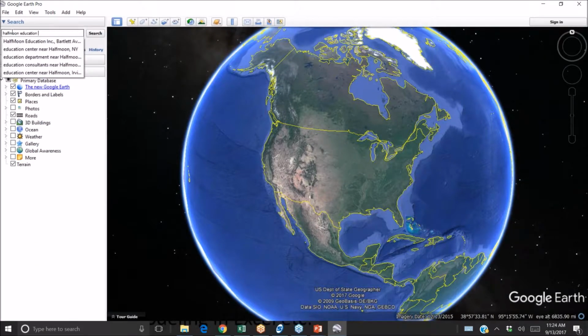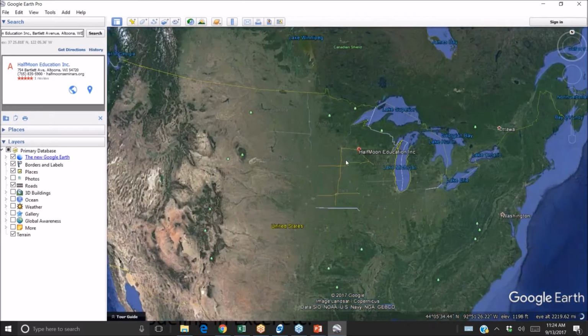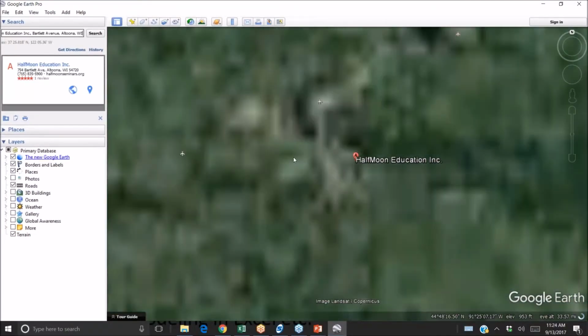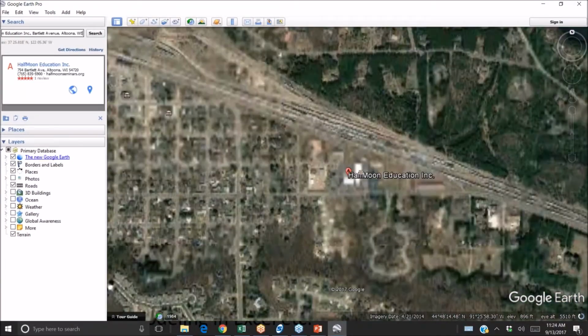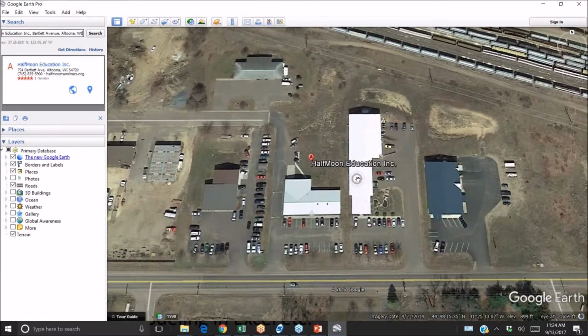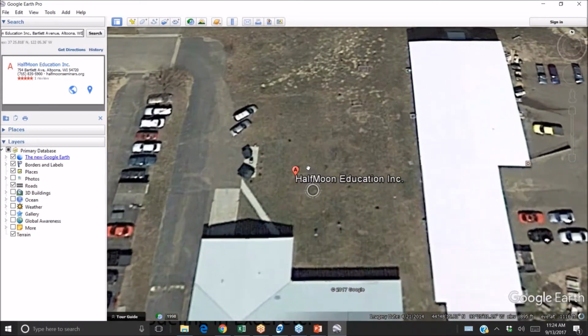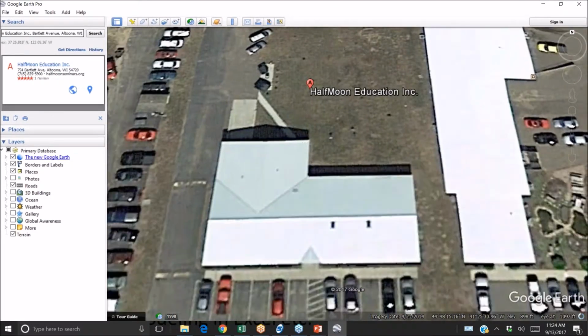So there's a lot of reasons to abide by proper fire code setbacks and not use every inch of the rooftop for your solar array. And one of them is that it lets you do your designs with remote assessments with a little bit of wiggle room in case you misclick on Google Earth.